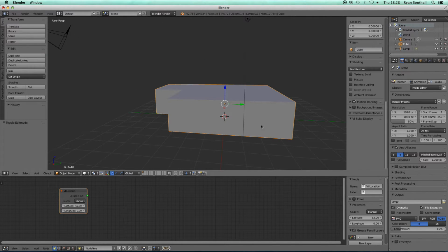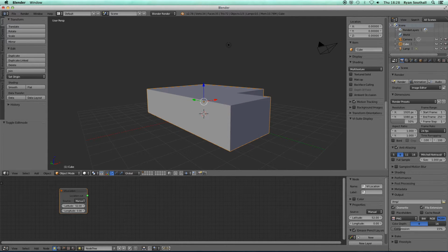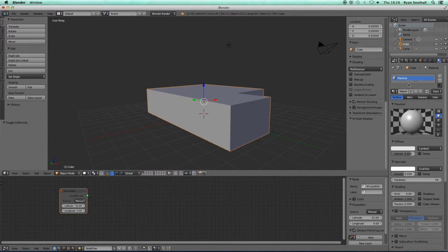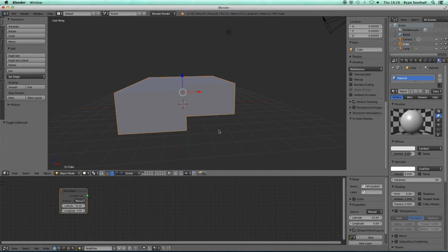Okay, fine. Now this default cube would have come with a material already associated with it. I can see that material, Blender's default material, in my material panel. Now for a lighting analysis I need to specify the characteristics of these face materials, and I can do that within this material panel.